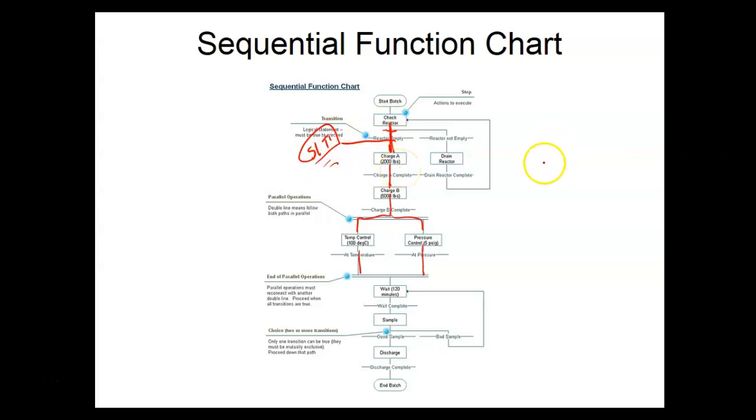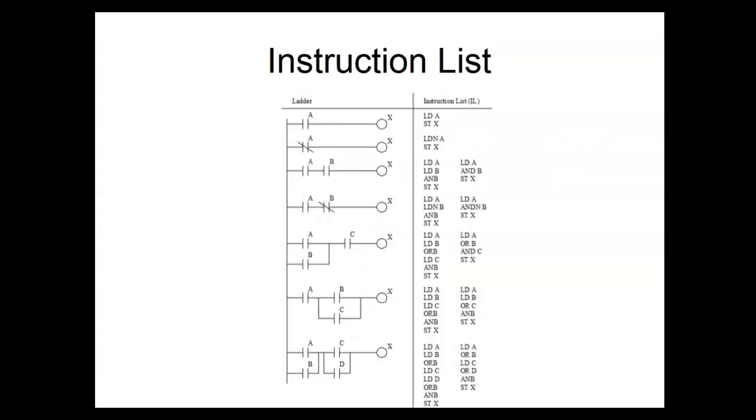And by the way, AND is done with this. So you'd say like switch 1 and switch 2, and you would put that, and then if all that was true, then it would go to the next step. You know, so I'll show y'all some of the programs that's written. This would actually be the way it looks, but Siemens made it a lot simpler to understand, and you'll see how easy it would be to program a PLC that way.